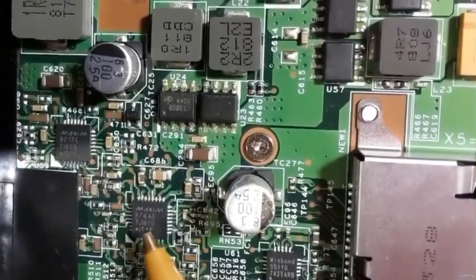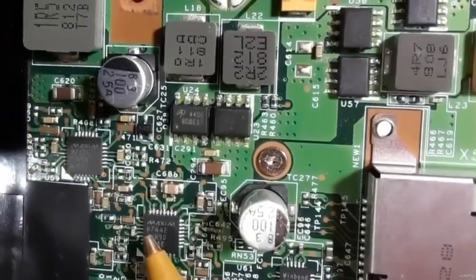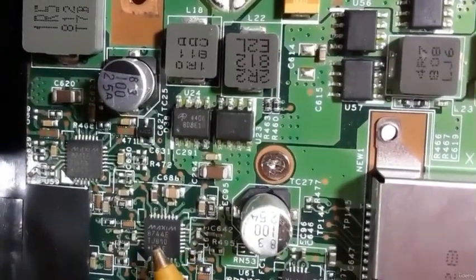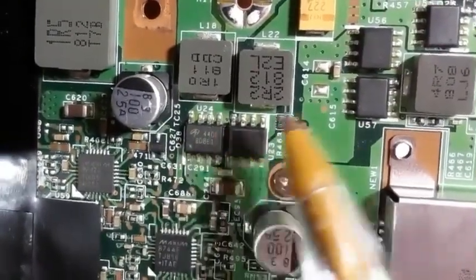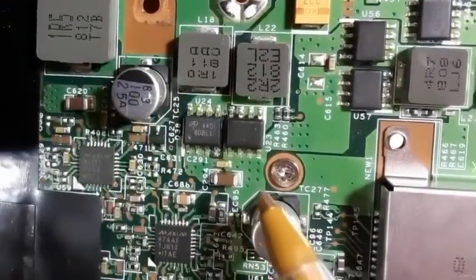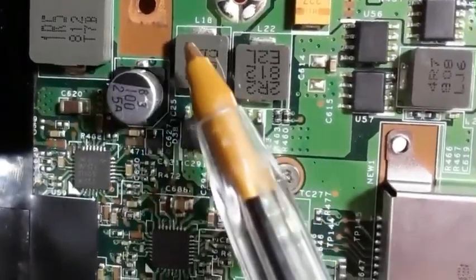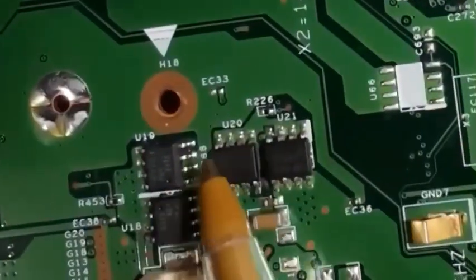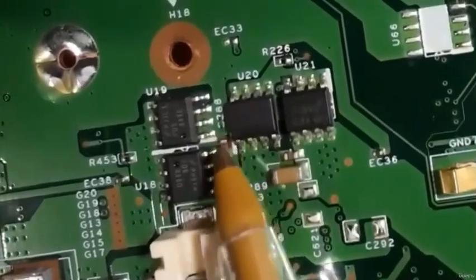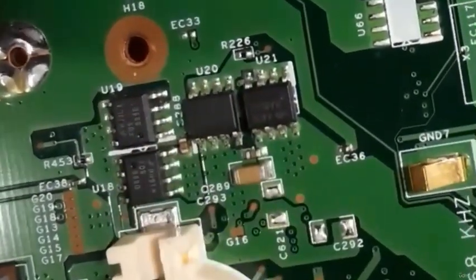So as you can see here, we have 8744A, the Maxim. 8744A. This is the IC that controls these two MOSFETs. Okay, so this is the 3.3 volt and 5 volt circuit. We have these MOSFETs and these two inductors, and also we have other MOSFETs on the other side, as you can see. Okay, this MOSFET, this is the back side of the 3 volt 5 volt power circuit.